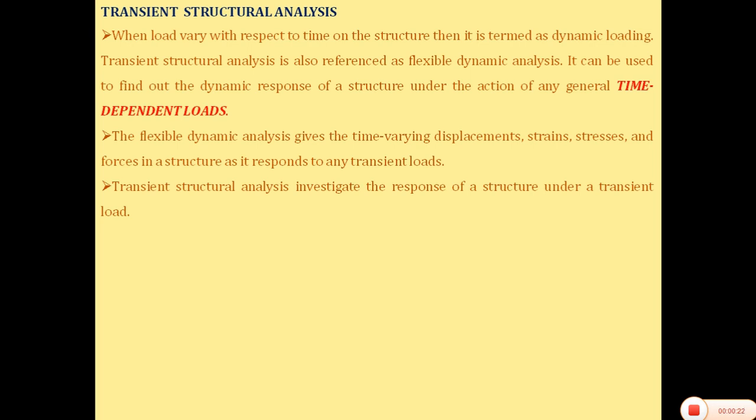When load varies with respect to time on the structure, it is termed dynamic loading. Transient structural analysis is referred to as flexible dynamic analysis. It can be used to find out the dynamic response of a structure under the action of any general time dependent load. In short, in transient structural analysis, load changes with respect to time. Here there is no constant load, the load is changing with respect to time.